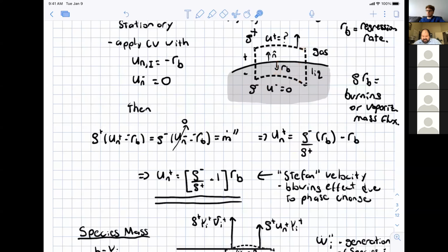And so if the net flux relative to the surface has to be conserved on both sides, that means that the gas vapor is going to accelerate to on the order of 1,000 times higher than the liquid.